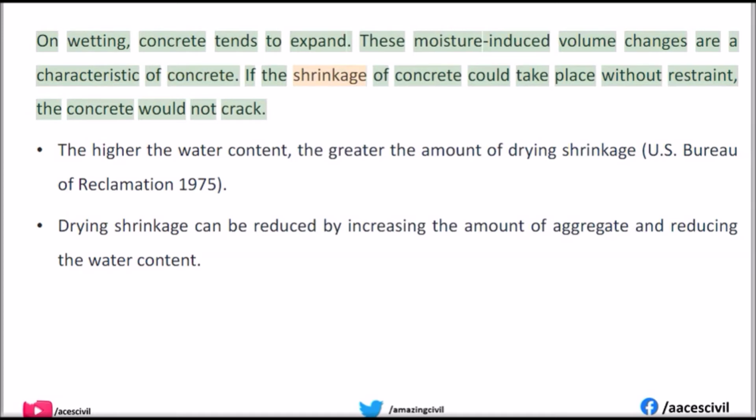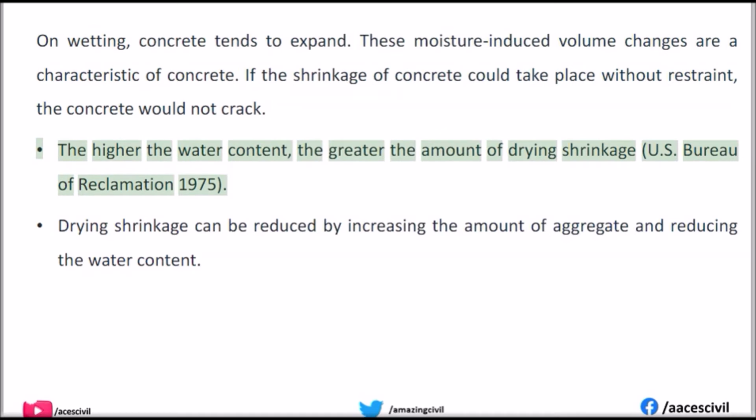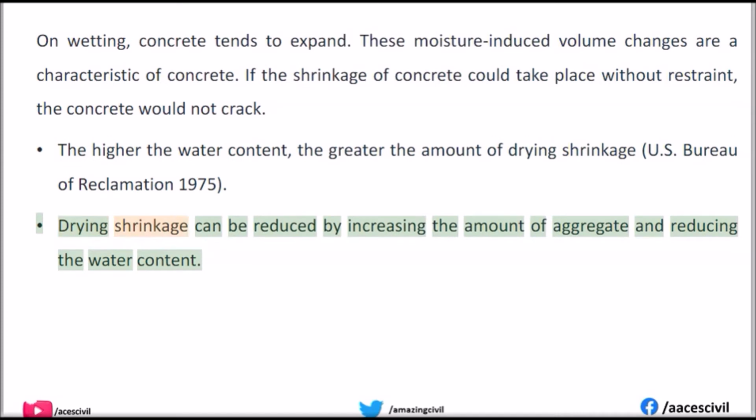If the shrinkage of concrete could take place without restraint, the concrete would not crack. The higher the water content, the greater the amount of drying shrinkage. Drying shrinkage can be reduced by increasing the amount of aggregate and reducing the water content.